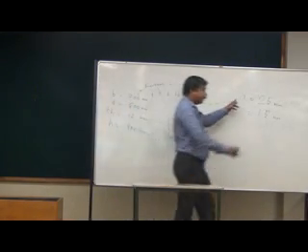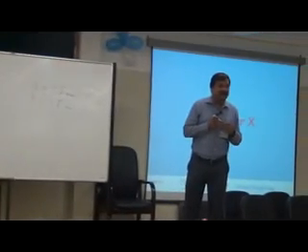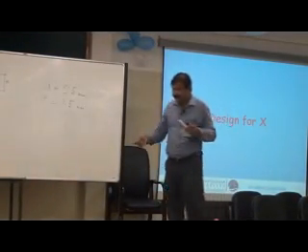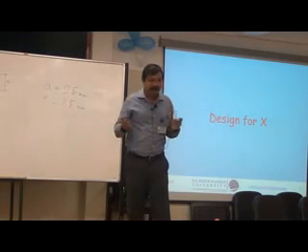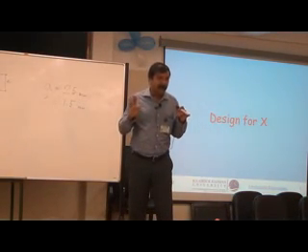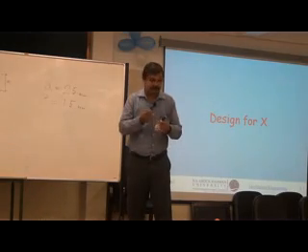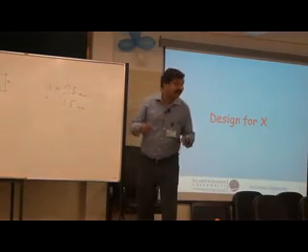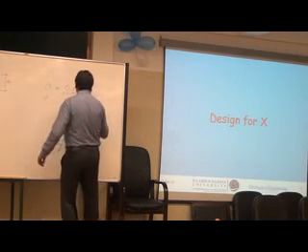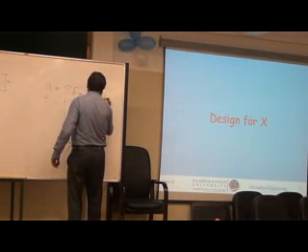Then, this A, 25 mm, the dimension of the legs. Are you bothered if the dimension is 10 mm from the functional point of view? No, you are not bothered. But it is a column, it should not buckle. So this is also designed for strength. So these dimensions are also decided for strength.